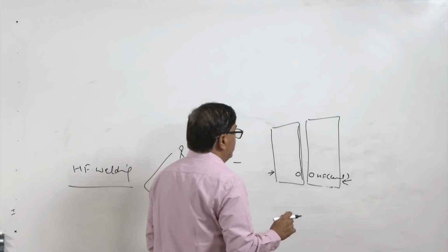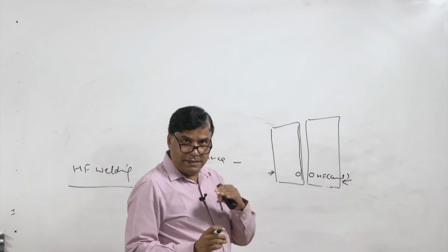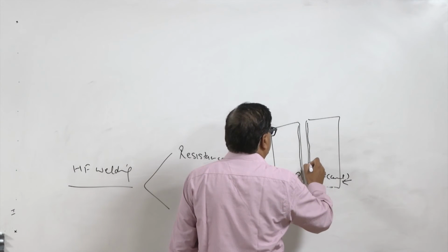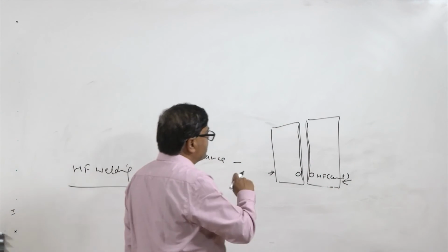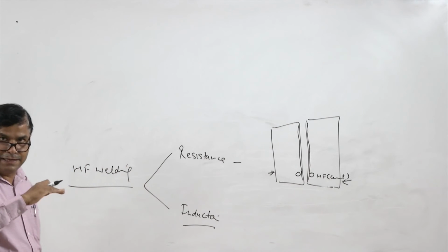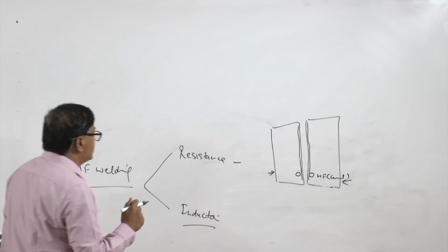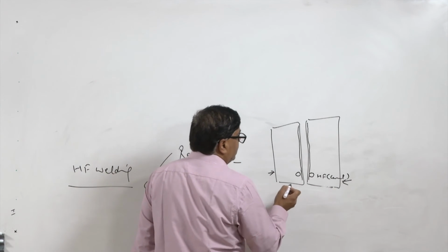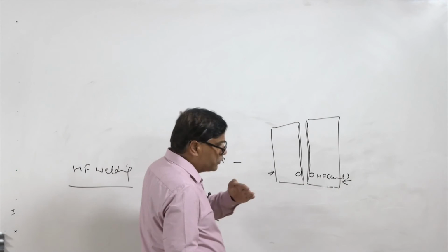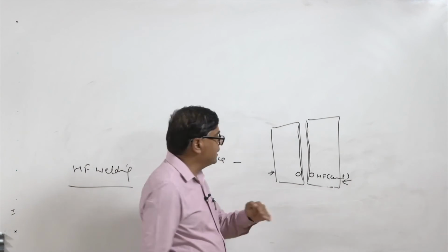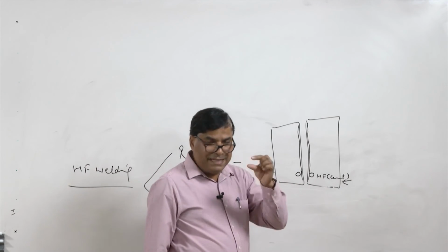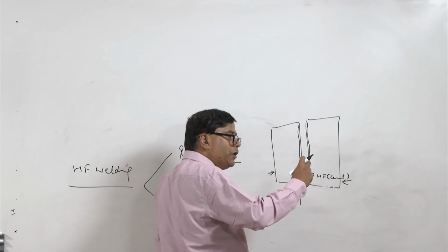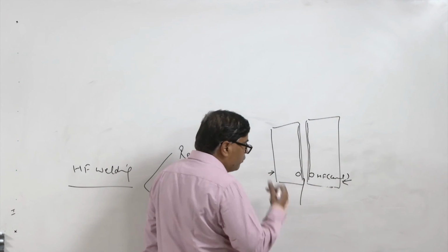It does not flow across the thickness or across the cross section, but passes very near the surface layers, and this feature is found very useful in the sense that instead of the flow of current through the entire section or entire thickness, it flows only through the near surface layers, which ensures that a very small volume will be experiencing the flow of current.